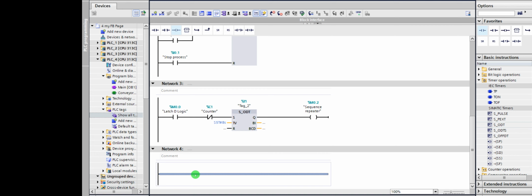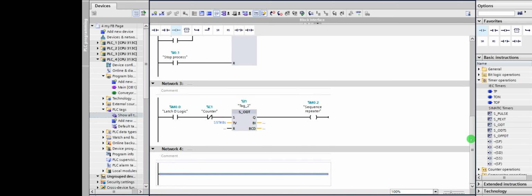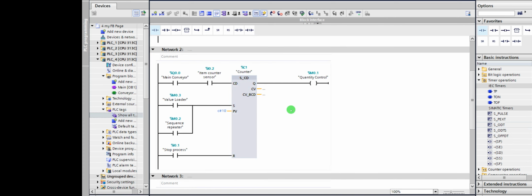Okay, so this counter would be product counting sensor. Do we have product counting sensor here? Okay, quantity produced. So we're going to have this bit and now have count up. This one is a counter that will count down. Counting down meaning that we want eight items to be completed in one particular sequence. So this one will count 10, 9, 8, 7. So you're going to count down. When you count to 0, it will now deactivate conveyor. So that is why we are using count down.